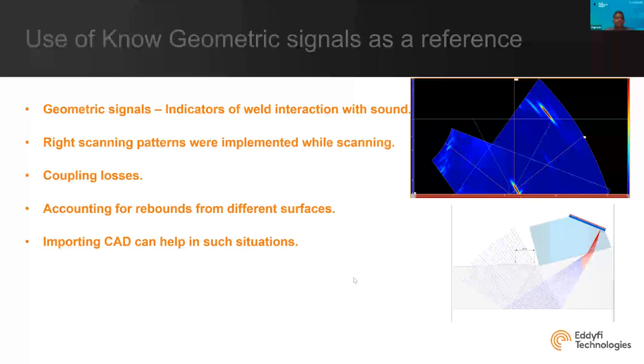Now, to understand these, what we have done is we have introduced some tools, like importing of a CAD file in the system that is being used to perform these kinds of ultrasonic inspection. When you import this, you generally get a rough idea, or you already know that my ultrasonic beam should follow these rules of physics and should be hitting certain areas. So an operator who is less experienced, less skilled, can quickly come to a conclusion, okay, this is what I'm going to use, provided we have a good CAD drawing that we can use.